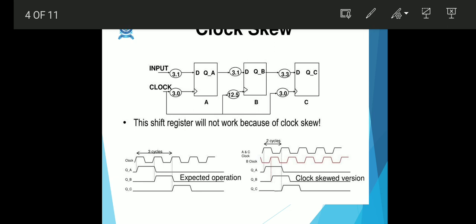Clock skew is introduced between two synchronous nodes and must be smaller than or equal to the clock period. The timing period will change in each case. The major difference is clock arrival time across the chip.